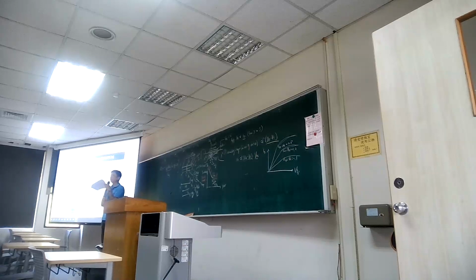That is for the BJT. But for the MOSFET we discuss here, we build up a channel, which is the minority carrier. This channel is proportional to the voltage we apply, and we have an electric field built up, which means the carriers are freely movable inside this channel, proportional to the electric field we apply. So it is drift current.